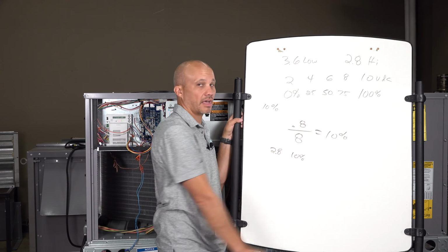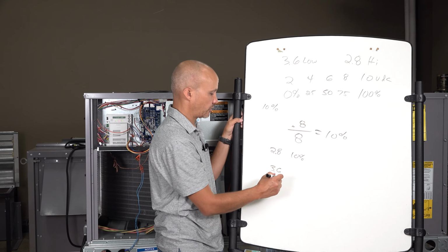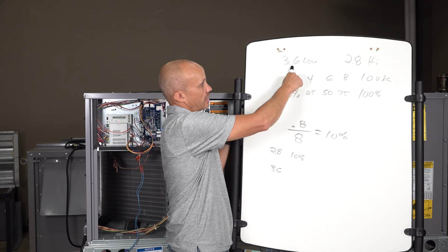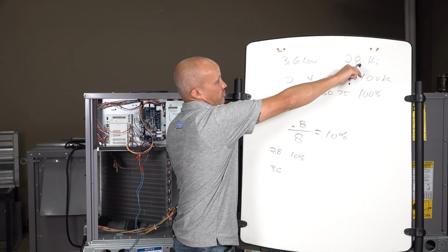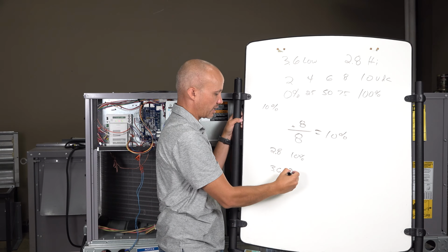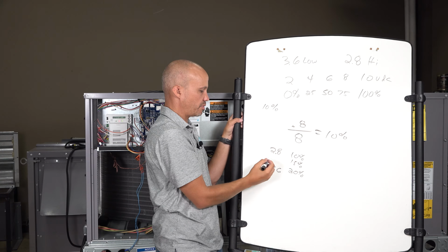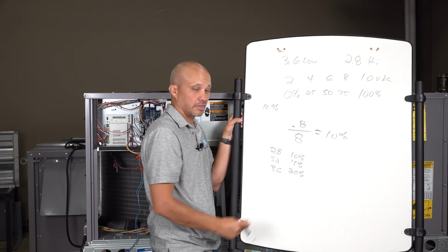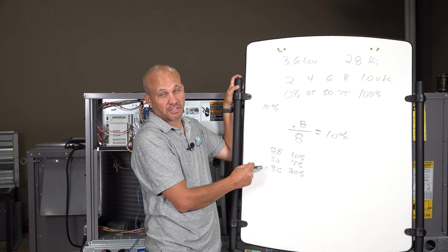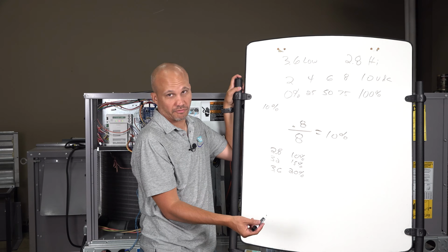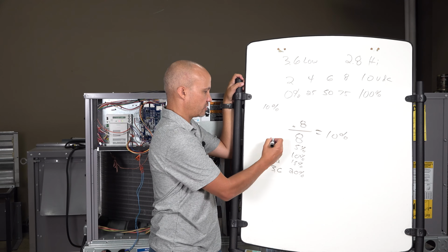So our default high fan speed was 10%. 3.6 volts, excuse me, is another 0.8 above that, right? So 0.2 to get to 3, 0.8, so that's 20%. If I wanted 15%, that would be 3.2 volts. So instead of doing this math all the time, you may want to just make a chart like this once and never think about the math again, because most of us aren't here for the math fun, right? So 5%, that would be 2.4 volts.